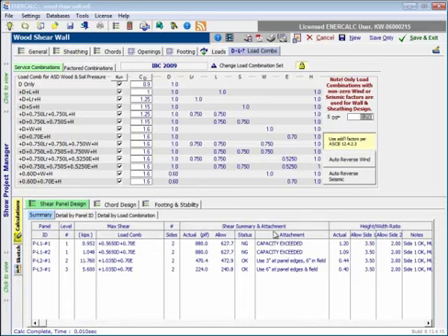The shear summary and attachment category shows us the actual shear in units of pounds per foot, the allowable shear in pounds per linear foot, the design status, whether it's okay or no good, and then a comment about the attachment.